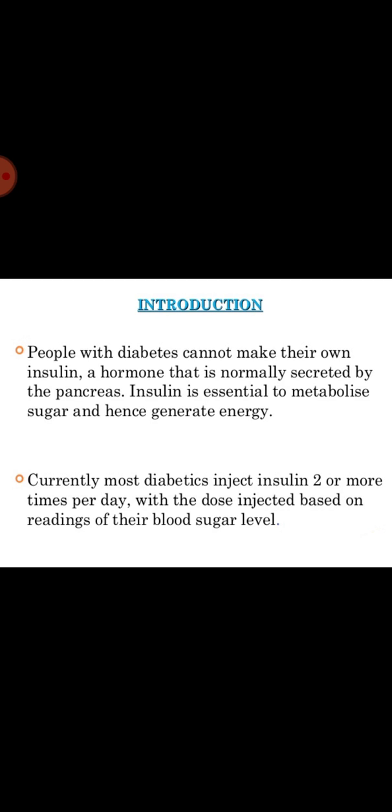The various means of achieving peristaltic action are cam-operated fingers pressing the tubes in succession, a rotor on an eccentric shaft which squeezes an eccentric cylindrical liner, and a row of eccentric cams which moves the cam follower, producing a clamping effect and imparting a squeezing action to plastic tubing, among others. They are self-priming as no valves or seals are required, and the accuracy rate is high. Peristaltic pumps use speed control of the device motor, which may be a synchronous electric motor.